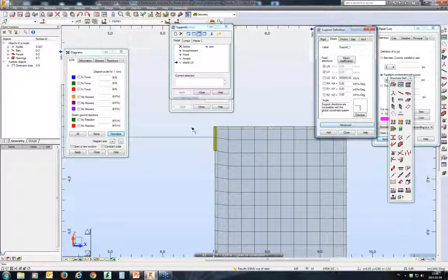So rather try to keep the story end and beginning at the same level as much as possible, even for the sake of the definition of seismic analysis later on and checking the results for the stories. So I think the idea is to simplify the model as much as possible, but do not oversimplify it.